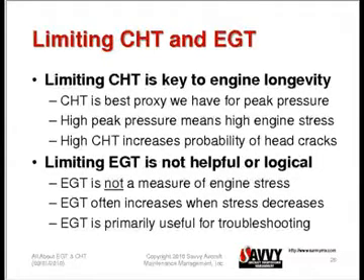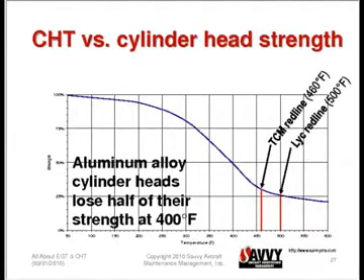Limiting EGT is not particularly helpful or logical. EGT is not a measure of engine stress, and it often increases when stress decreases. EGT's primary use is for troubleshooting. Let me talk a little bit about the benefits of limiting CHT.